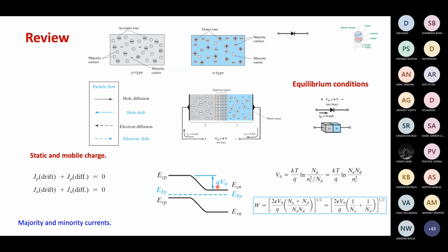One thing I would like to highlight is that if we try to measure voltage across any device, any conductor, any semiconductor, with any electronic equipment, be it a potentiometer or a voltmeter, it measures the difference in the Fermi level on both sides. Just keep this in your mind: any measurement device measures the difference in the Fermi level across the device.